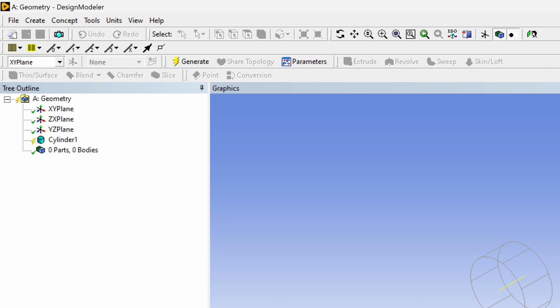You can change how this is being built. Like when you choose add material, what happens is if you add a second object that somehow shares some parts of its body with the current object, they are going to be unified, right? Without the need for any further operations, right? So this is fine when you just want to add the beam structure, but later on when you want to build the control volume that should contain the air surrounding this beam structure, we need to change this to add frozen. You see the two options here. Well, you're going to keep the add material.